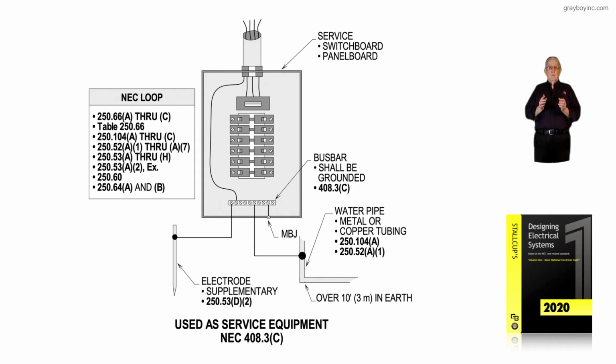And then notice that as long as the phase conductors, like the 4/0 terminating at that 225 amp main, do not exceed 1100 kcmil for any one phase, then everything is going to be the same size in that panel board. That main bonding jumper that you see would be number 2 also, sized from Table 250.102(C)(1).